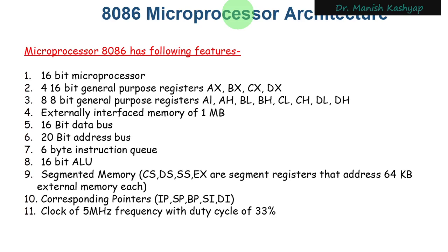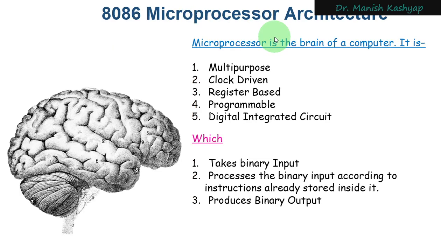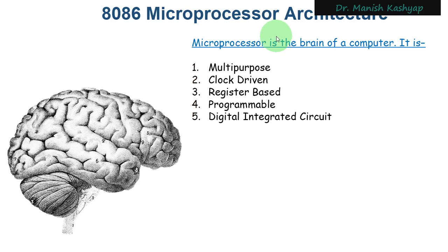Now program status word, as we saw in 8085, was a combination of accumulator and the flag bits. So in 8085, program status word meant a combination of accumulator as the higher byte and flag register as the lower byte. However, in 8086, the program status word will simply mean the flag register only. So flag register and program status word are the same. You do not have to club the accumulator with them. If you see the flag structure, let me again bring that slide of the flag register for you.